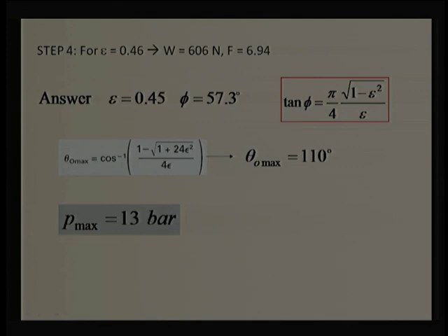On one side it is a negative, but bearing materials are mostly able to sustain more than 5 megapascal. So why worry about 1.3 megapascal, let it be. If the bearing length gives all other advantages, we should go ahead with the larger length.